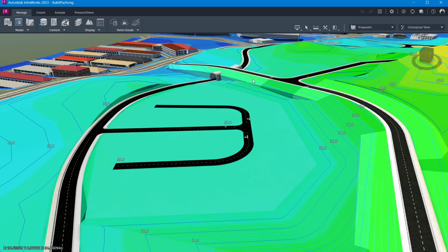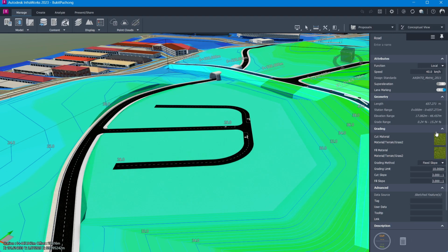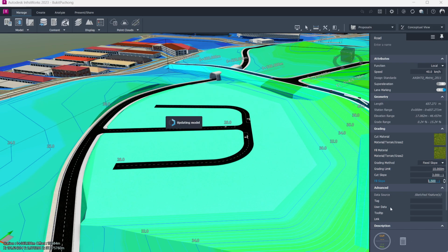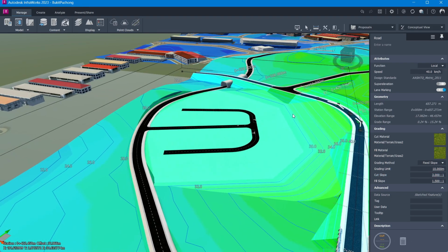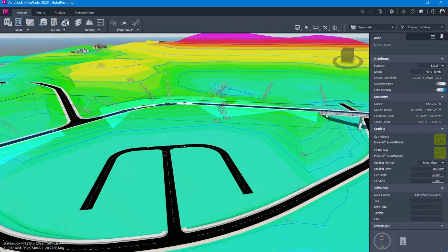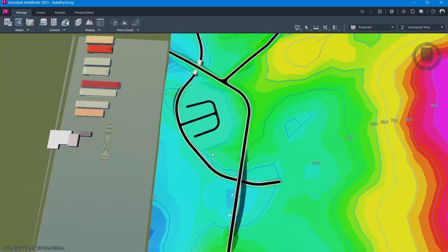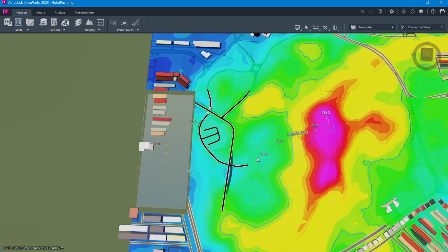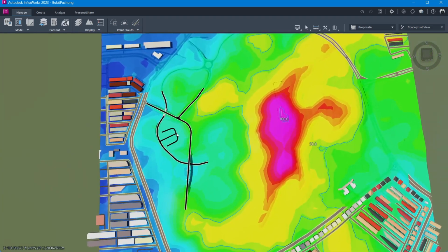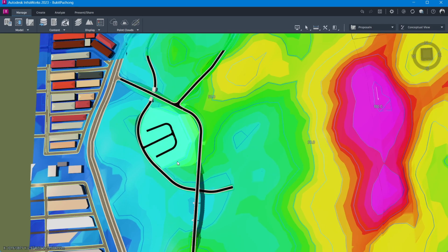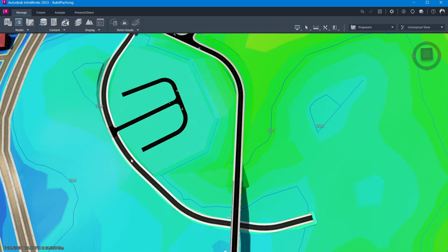See here, for the road, we can manage to cut the slope. Even though here it is 3 over 1, still too gentle, so we can set it. We can set 1 over 1.5 over 1. So when we cut here, we can change it, but not on the grading. Grading is too gentle. So what we are going to do is import this model into Civil 3D. Then we utilize this boundary to create the grading in Civil 3D.